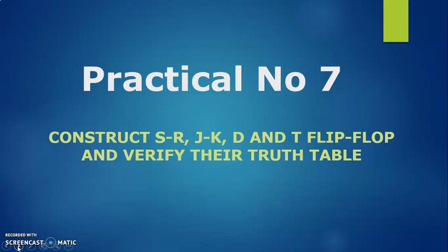A latch has an enable input, and as long as it is active, the latch output will keep changing according to the changes in its input. In other words, a latch is a level triggered flip-flop. But the flip-flop is a sequential circuit which generally samples its input and changes its output only at a particular instant of time and not continuously. Flip-flops are therefore said to be edge sensitive or edge triggered rather than being level triggered like a latch.